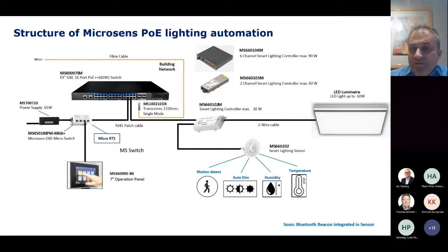Normally, if you run a 24 port 90 watt switch, you can connect devices to this switch from 30 up to 90 watts. According to the exchange protocol LLDP, the device is smart enough to recognize what kind of controller is connected and switch down or switch up the power which is delivered to the smart light controller.